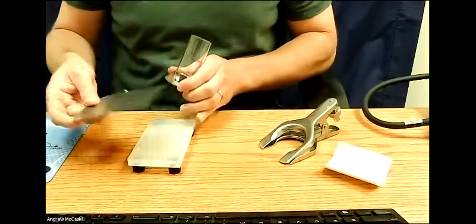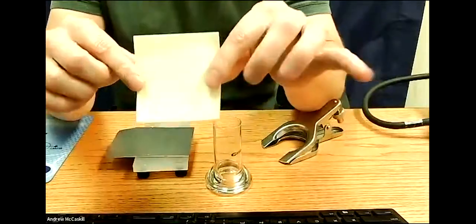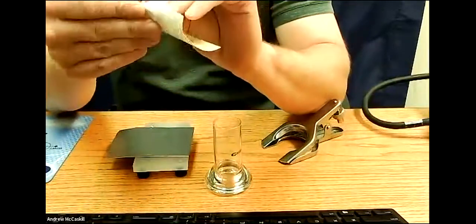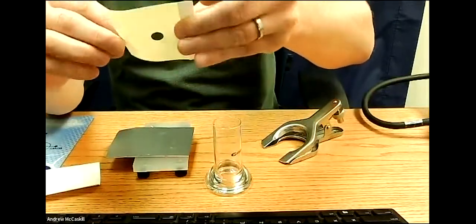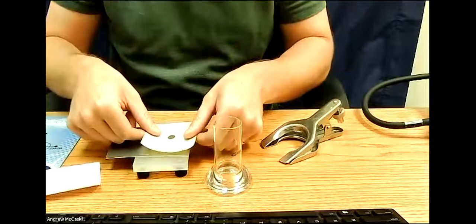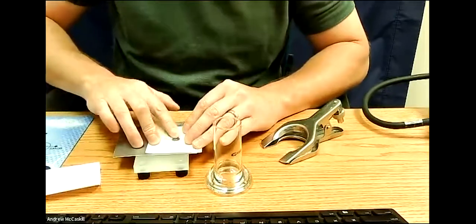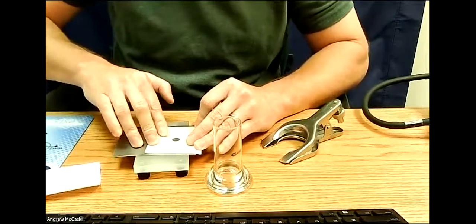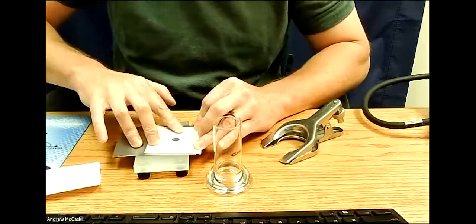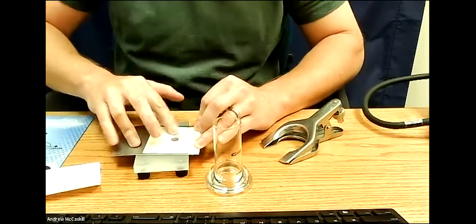So stainless steel is going to sit right here on the top of the plate. I have my sample mask. Let me open this up so you can see the whole thing. So here's the sample mask with the exposed area right there. I'm going to take that, put that right down here on the surface, like so, and then I'm going to make sure I have good adhesion, particularly around the exposed area, because you don't want bleeding underneath the mask.